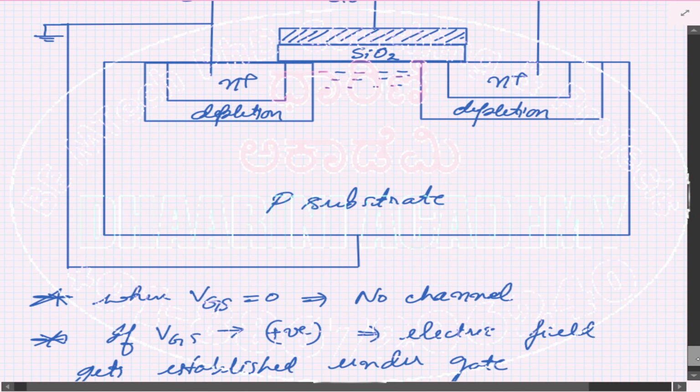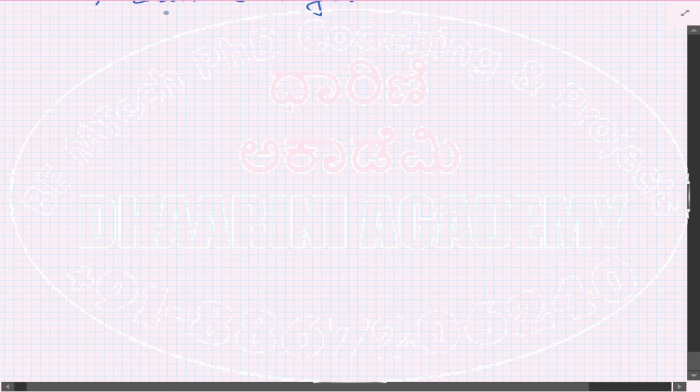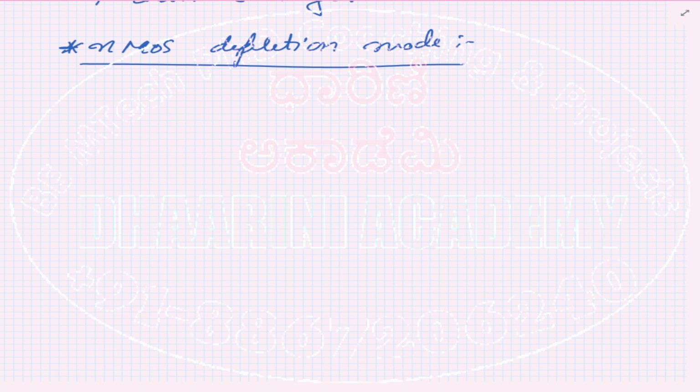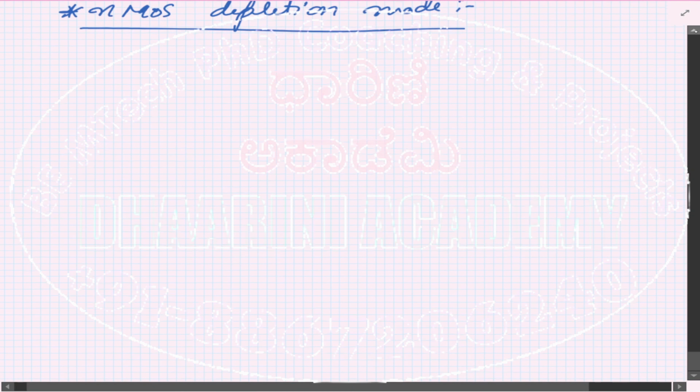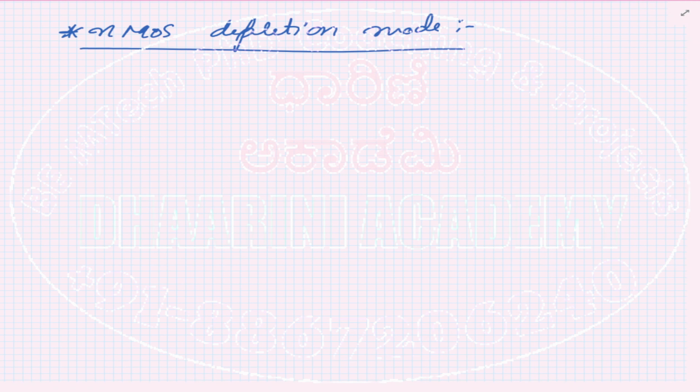Now let's go to the same N type, but it is a second mode of this. It is called a depletion mode. So this is NMOS, depletion mode of MOSFET. The outer structure still remains the same, except the fact that there is an inbuilt channel that exists. That's the only difference now.